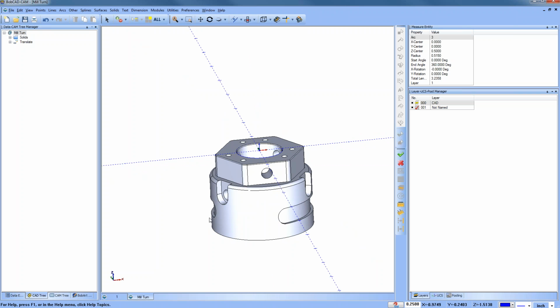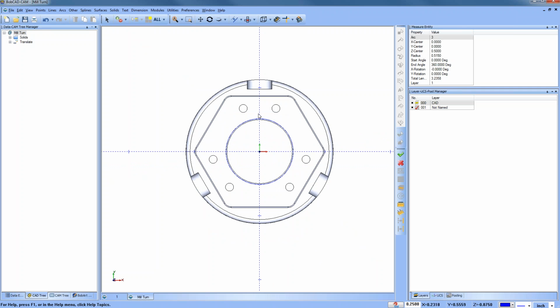The next thing I'm going to do is rotate it. But before I do that, I'm going to create some wireframe for the front pocket face here, okay? Because I'm going to profile this. I'm going to chamfer it. So what I want to do is generate some of the wireframe here while I'm here. So I'm just going to create a layer called, you know, pocket, or you can name it whatever you want.